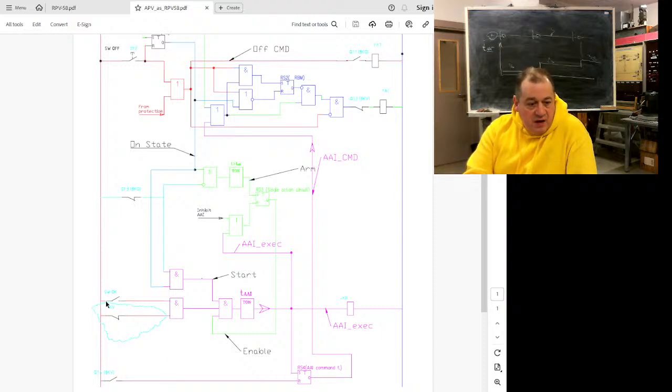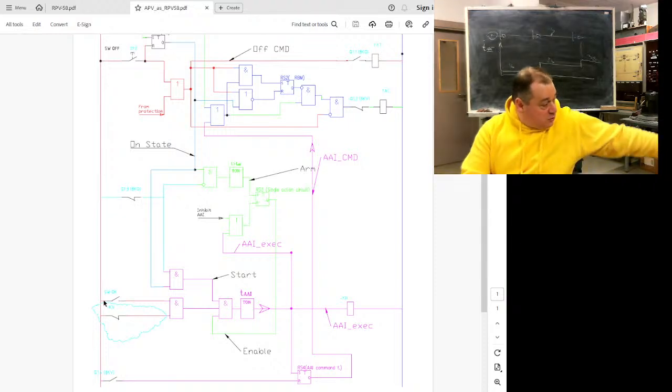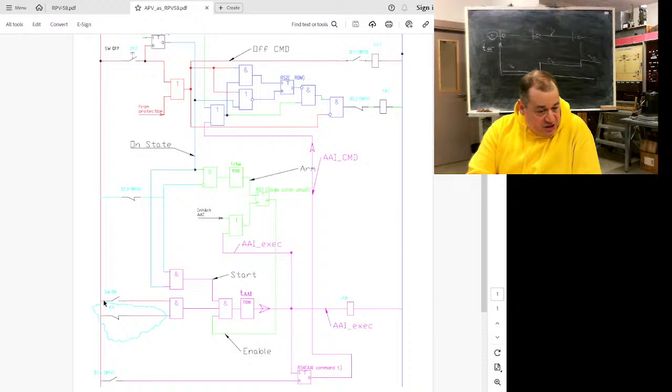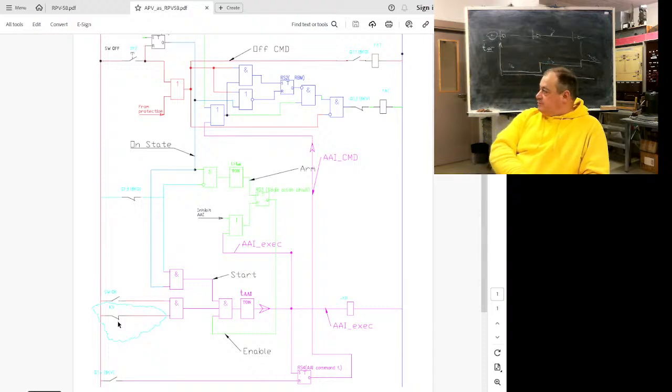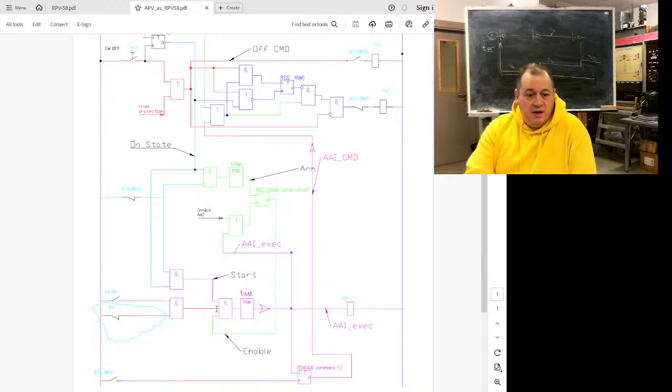But what's this? Switch is okay. One, it's a pressure circuit. We have sufficient pressure. This one, for example, has a pressure sensor. And also sufficient voltage can be used. It's a tricky thing, but to prevent system problems, we will not perform auto reclosing if bus voltage is not sufficient. We will not increase load in an emergency state. So we have start, switch okay, voltage sufficient, enable from single action circuit.